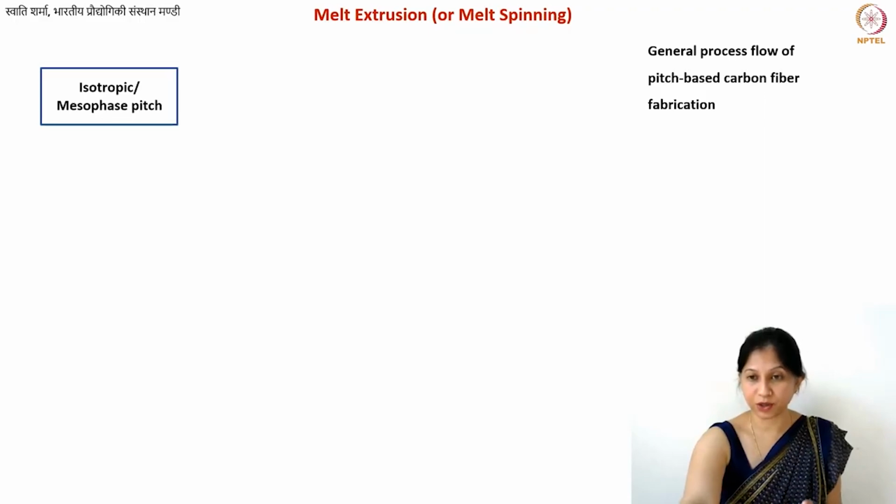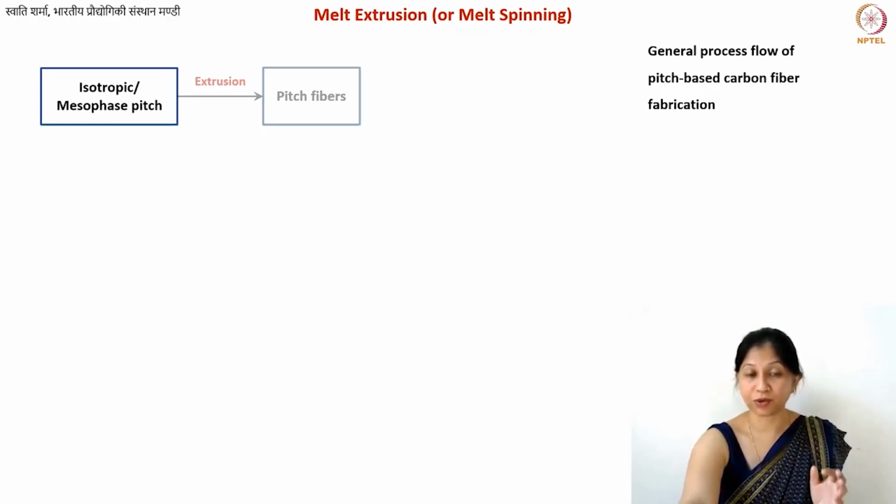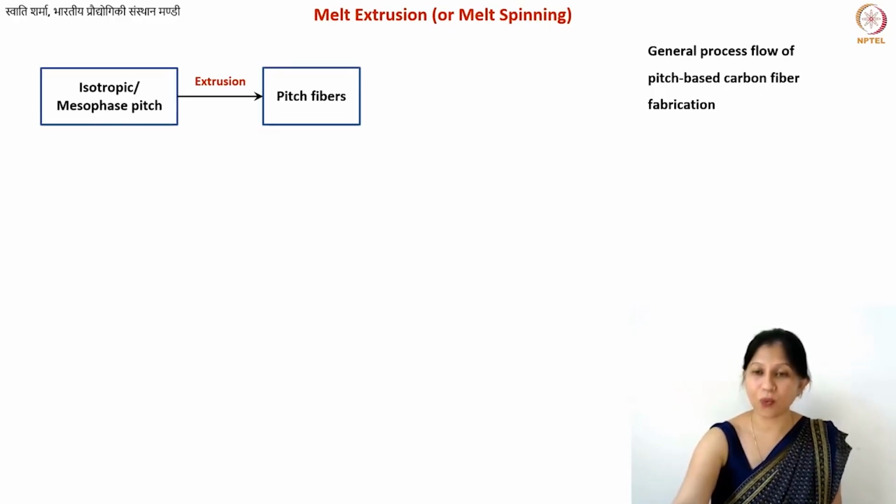Isotropic or mesophase pitch. You will take any type of petroleum pitch, and then you will perform the extrusion as I have shown previously using this spinning setup. Okay, now you have pitch fibers. What do you do with pitch fibers? Do you directly carbonize them? Now there is one more stabilization step in between.